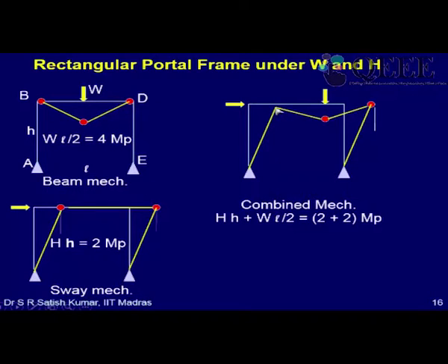So there will be no hinge forming here, and here it is closing by theta, and here also it's closing by theta. So here it will close by 2 theta. So it will become MP into 2 theta, and here again it was sort of bending by 2 theta, and here no, right? So it is 2 theta. So MP into 2 theta. So 2 plus 2, 4 MP theta will be on the right hand side, and that gives you a combined mechanism.